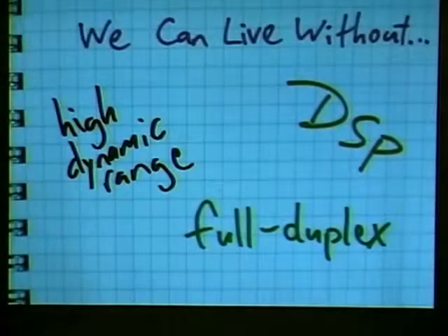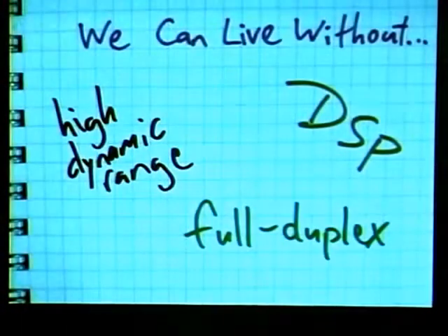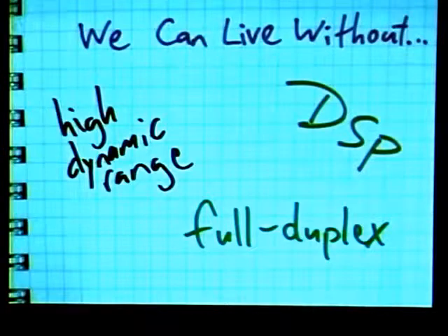Traditionally, the conventional wisdom in the software-defined radio community is that we need to represent digital signals with 10 to 16-bit numbers, 10 to 16 bits per sample. That's the dynamic range. And we think that we can get by with less than that. We think we can get by with 8 bits.